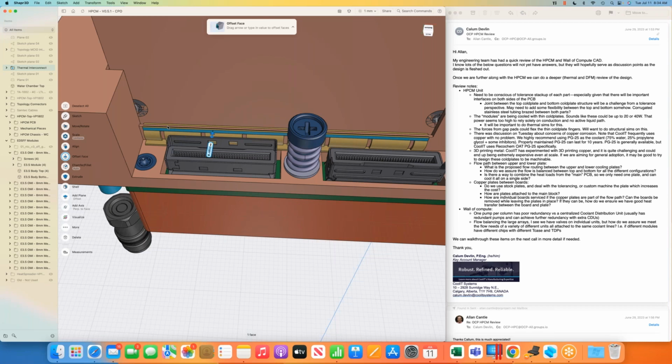But I think you were referring to thermal interface, right, Alan? That's the idea. An EMI gasket is a mechanical construct with a known Young's modulus, whereas with a TIM material, or some sort of thermal interface material, the Young's modulus can vary dramatically as well, depending on the temperature of the environment itself. Right. Okay. Yes.